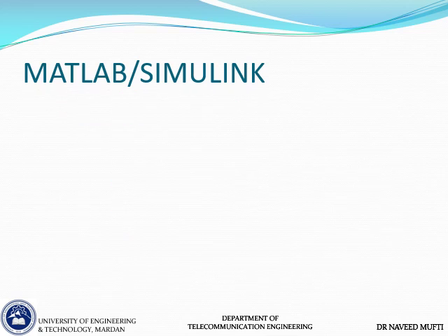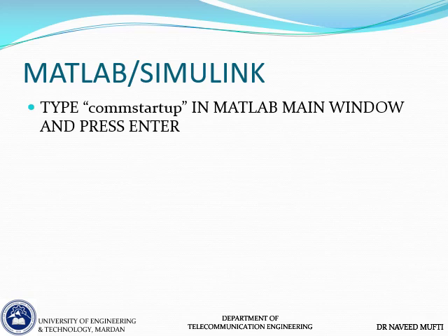So continuing on our discussion on MATLAB and Simulink, once you load MATLAB, you've checked your versions, you've got all the three things that are needed for this course. So you type comstartup in the MATLAB main window and press enter. That is needed before you simulate any communication system.